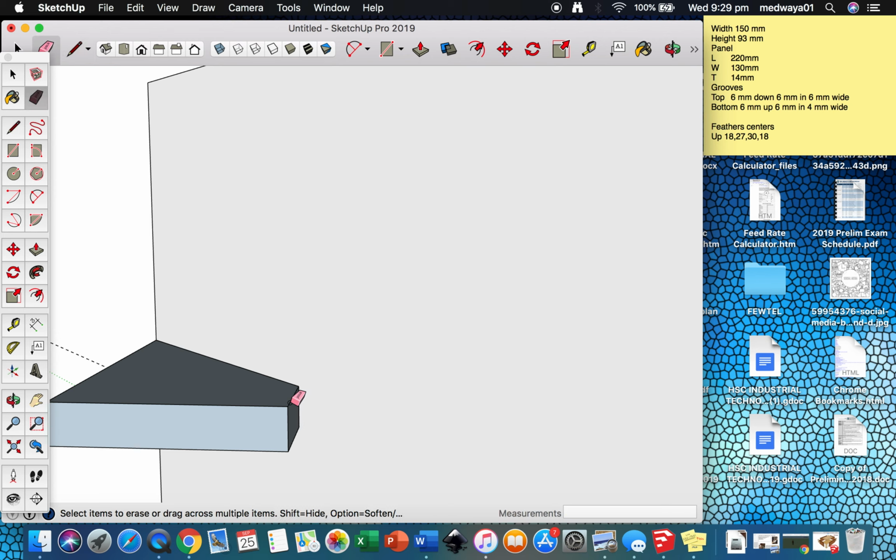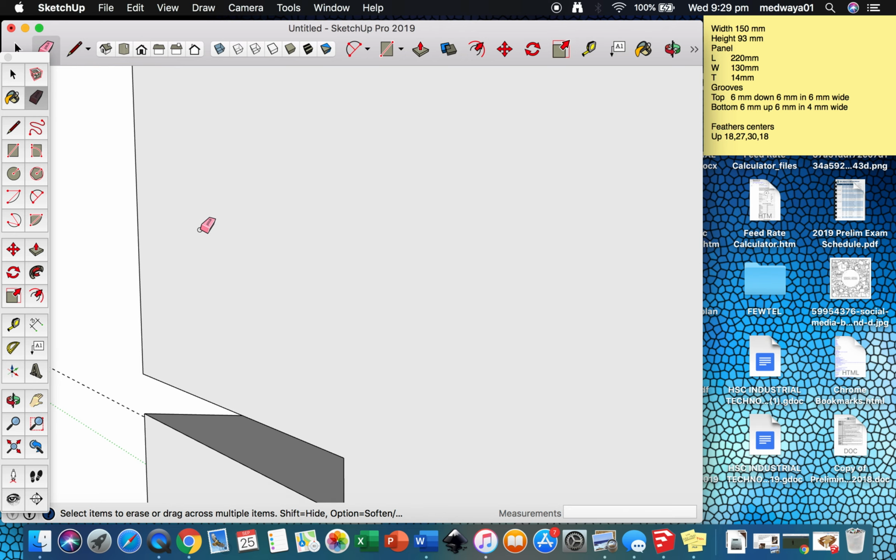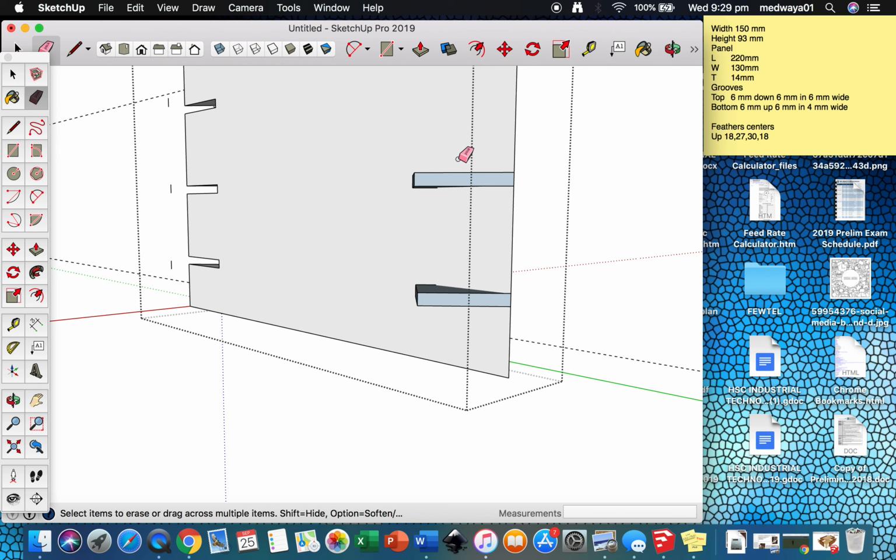Finally, draw that line down the back, endpoint to endpoint, erase the rest of the drawing. Notice that the surfaces disappear once the edge is gone. The surface needs to be surrounded by edges. That's one end, that's both ends. So I'll stop the video there, do this end, and then I'll start the video back again and show you what to do next.